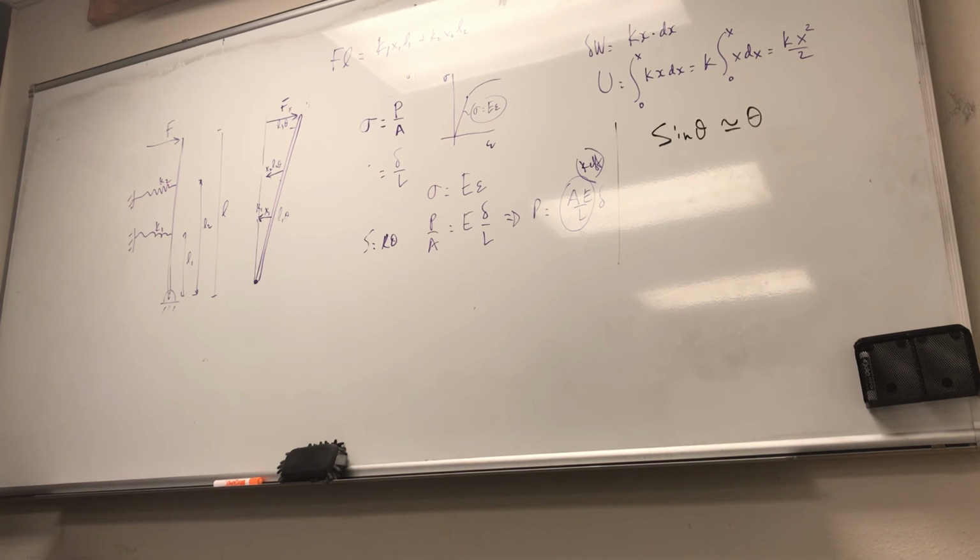Okay, now where do we use this mass? People who do, for example, vibration of multi-story buildings during an earthquake, you got a building that looks like very strange stuff, right? And then you go like, how is it gonna vibrate, right? Well, civil engineers look at that and say, hey, most of the masses of the buildings are where? In the floor, not in the walls, right?